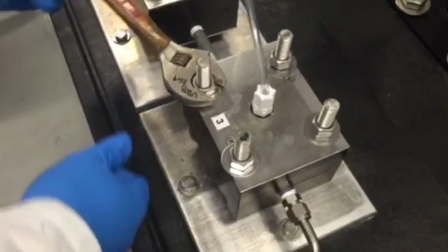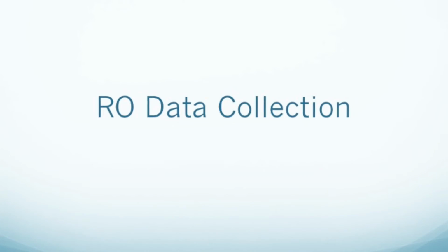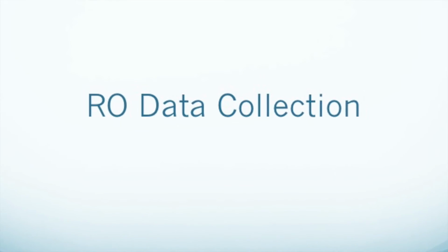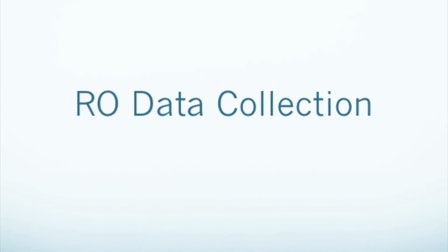Fill the feed tank with 9 liters of distilled water. Make sure appropriate valves and fittings are tightened and connected. Set flow rate to 2 liters per minute and adjust pressure to 100 psi. Turn on the system and purge all air bubbles from the system for 15 minutes. The first run will just be with distilled water.